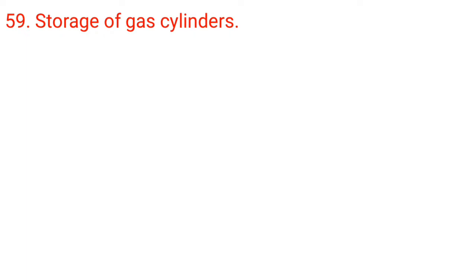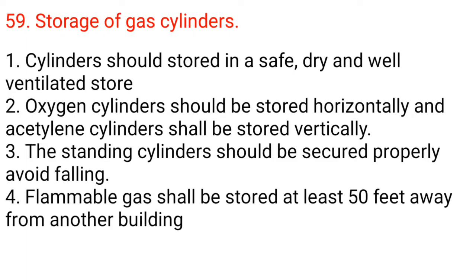59. Storage of gas cylinders. 1. Cylinders should be stored in a safe, dry and well-ventilated store. 2. Oxygen cylinders should be stored horizontally and acetylene cylinders shall be stored vertically. 3. Standing cylinders should be secured properly to avoid falling. 4.